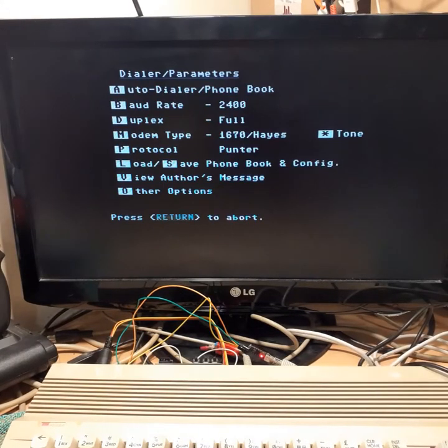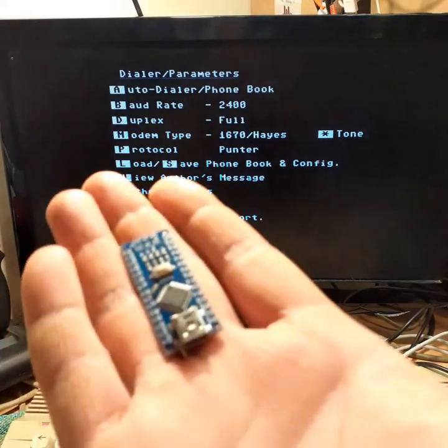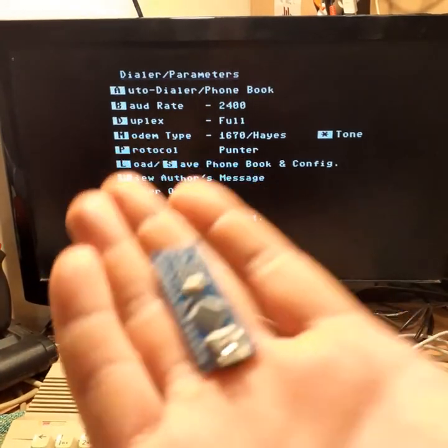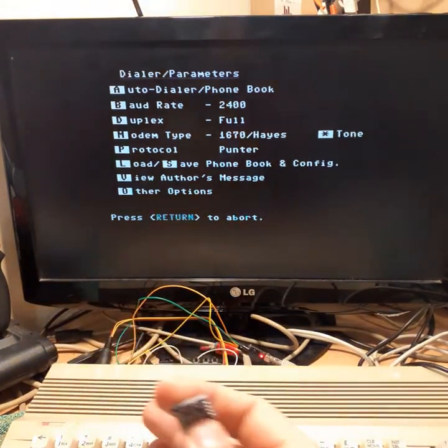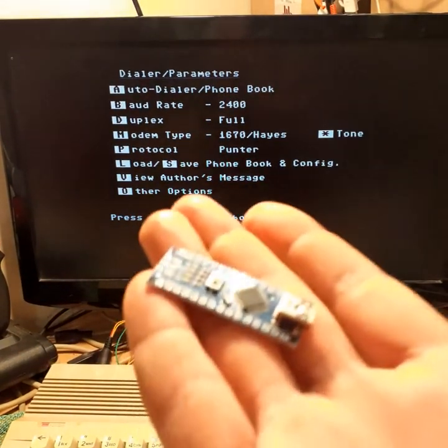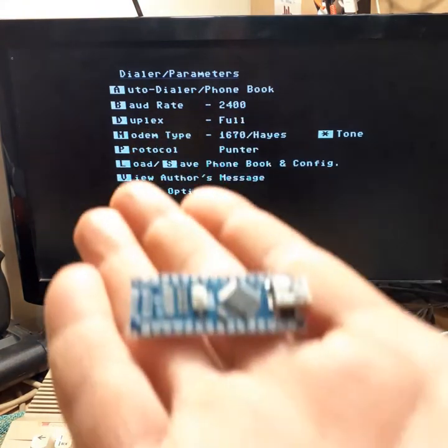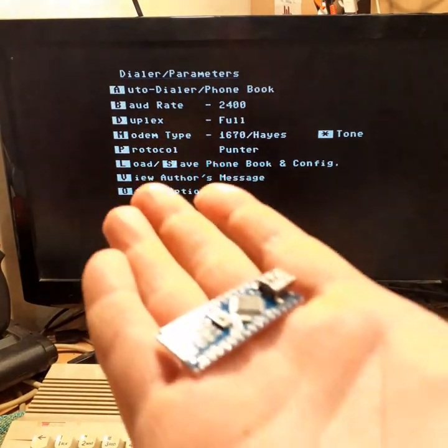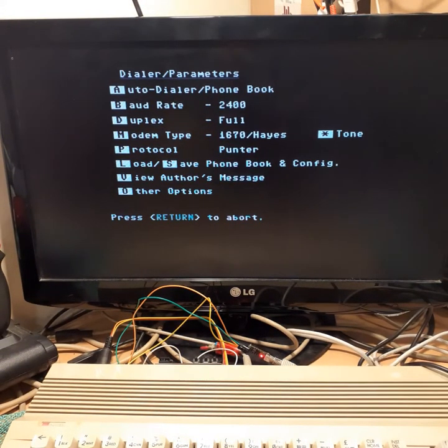So for conclusion, as I mentioned at the beginning of this video, serial communication of RS232 on Commodore 64 is more suitable for today's use with modern machines than it was back then, and that's absolutely true. So if you want to, for example, connect an Arduino board to Commodore 64, it's very easy. TTL on Commodore 64, TTL on Arduino boards, 5 volts on Commodore 64, 5 volts here, direct connection, no problem whatsoever. Raspberry Pi, of course, same thing.